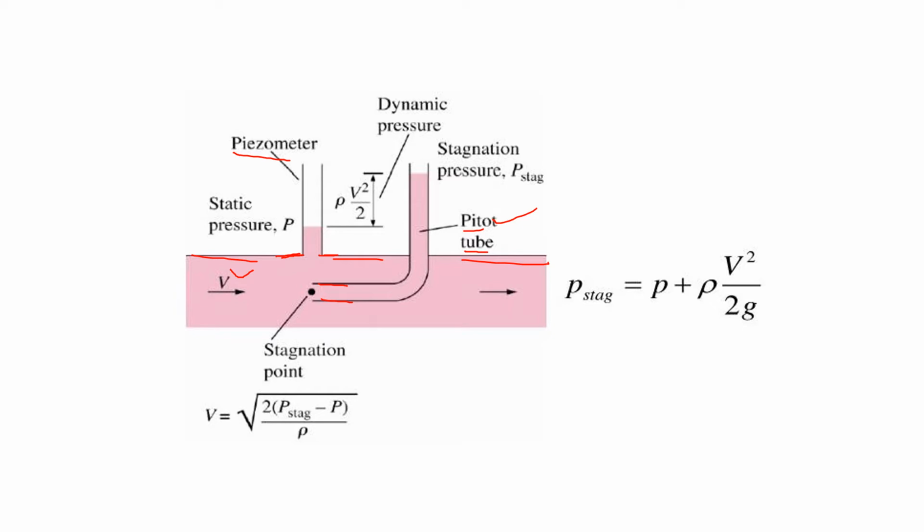So when I insert my measuring instrument in such a way that its surface coincides with the surface of the duct, then here I will have the fluid with 0 velocity. So we can attain our static state definition.